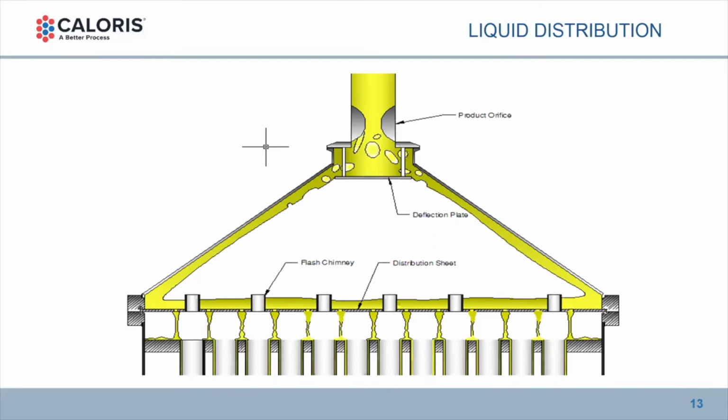because a little bit of extra energy is not bad. We want to make sure we are at boiling temperature when we get into the tubes. So we've got to restrict it a little bit as it comes in to prevent flash in the pipeline before it gets into the calandria lid. And now the first thing we want to do is distribute that against the lid of the calandria to dissipate and allow that flash to take place. So now the liquid, as it gets into the pan and onto the distribution plate, is at boiling temperature. And we've got a little flash vapor in this chamber here.